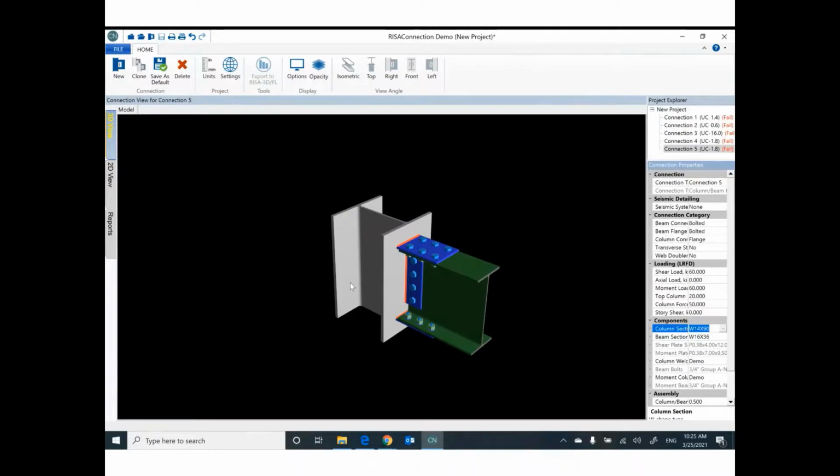How did you know this? Because this connection will transfer shear and moment. Why? How did you know this connection will transfer moment? Because the top flange is connected to this column by this little plate. And the bottom flange is connected to this column by this little plate. And the web is connected to the column by this plate. So we have 3 parts connected to the column, this connection is called fixed connection.